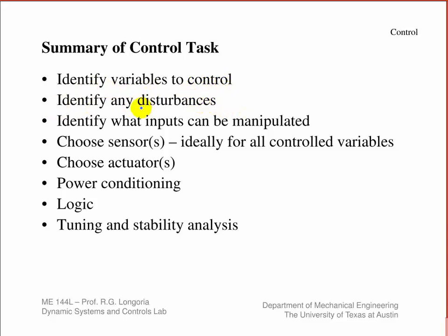You also try to identify what we call disturbances. In a control system, a disturbance is any input to the system that's not being controlled. For example, on that needle, where I'm using it here, I have a ceiling fan running, and you can see that it makes the needle oscillate sometimes, and there's a little bit of fluctuation if I have that fan too high.